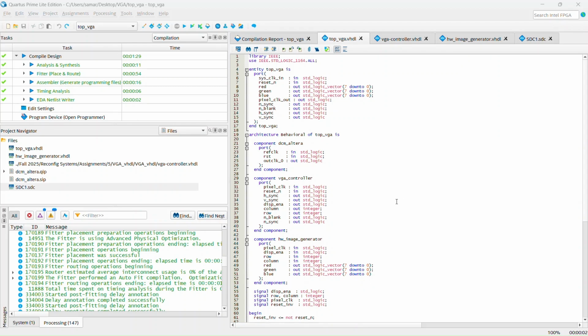VGA integrator. So you might wonder what the VGA is. VGA is nothing but a video graphic array. VGA is something that you need when you want to drive an image onto your monitor screen. Since your monitor screen is an analog display, you would need the VGA configuration. So the idea here is, we'll be using our FPGA to generate the image, and it will be sending out the signals of the image that is to be displayed on the monitor screen.